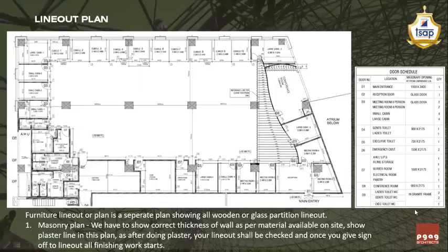While giving the height of the door, we generally give the height of the door from the FFL. Now I would like to explain why the FFL is written as 0.0 mm here. FFL is finished floor level, and why is it written as 0.0 mm? Because as per site conditions, you might find that the main entry level, the slab level, might be a little lower, like 50 mm or sometimes 75 mm lower than the finished floor level at the main entry. When you enter from this area, there is going to be a finished passage, finished area from where you are going to enter in.